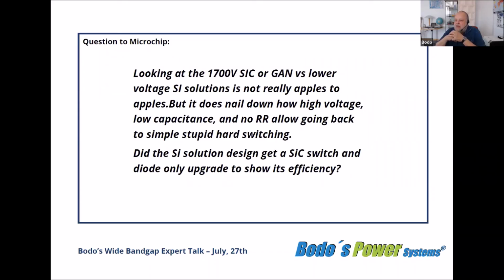Thank you, Felipe. Looking at the 1700 volt SiC device versus lower voltage silicon solutions is not really apples to apples, but it does nail down how high voltage, low capacitance and no reverse recovery allow going back to simple hard switching.